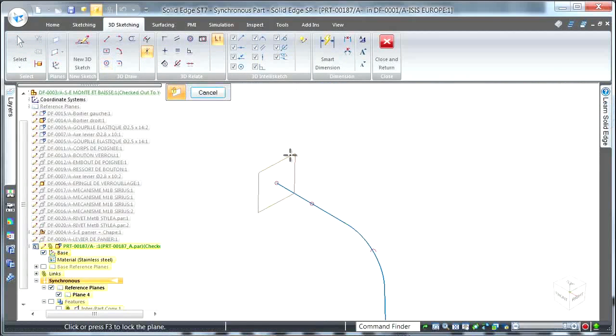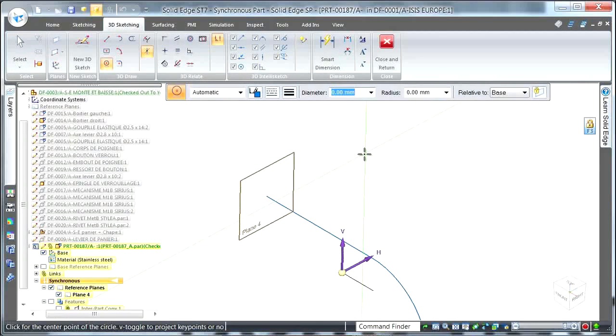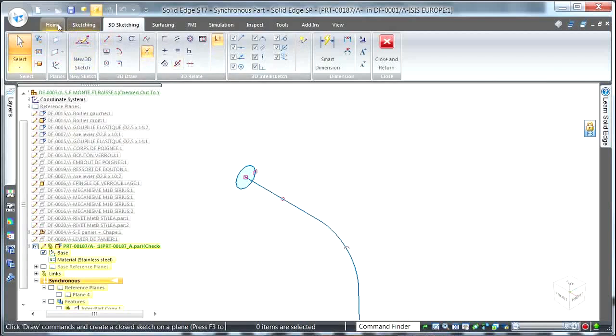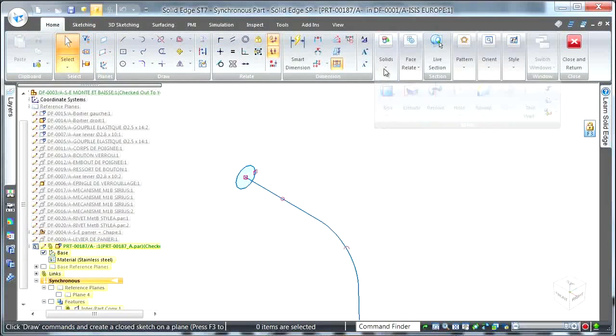So that little cylinder, why did we have that there? Well, it's the inside face of the little handle at the top. So we needed to take a measurement of that. We're going to sweep a profile around this 3D sketch path. So use the 3D measure tool to take a measurement. And then we'll pop a plane on the side here to do our sketching.